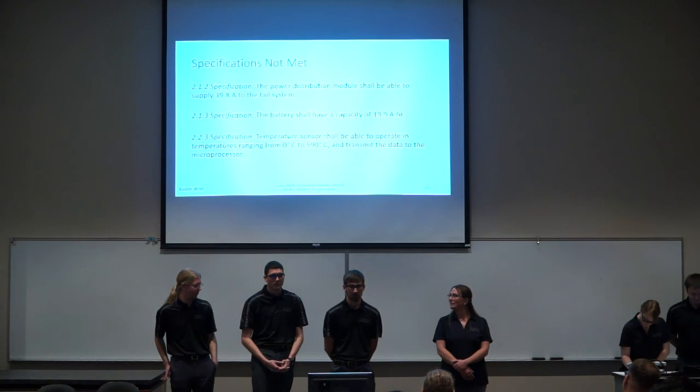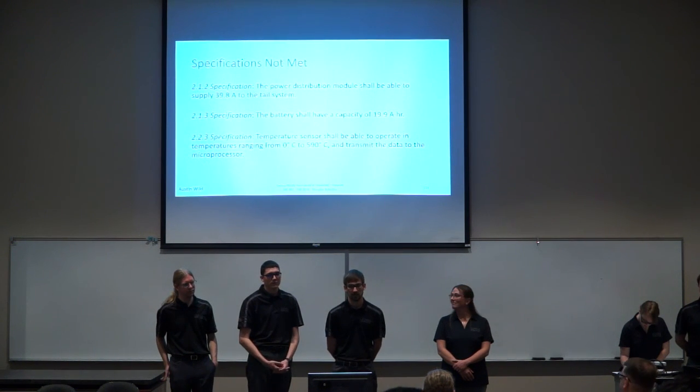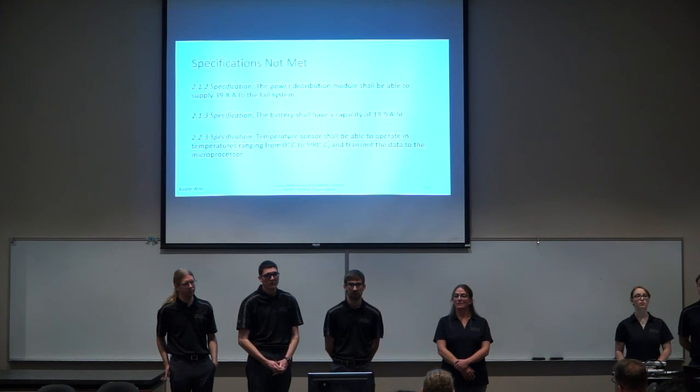In order to reduce costs in both money and size, we use a lower amp hour rating battery. What that affects is our battery life. We had calculated for a 30-minute battery life, but given both, we will be fine operating off 15 minutes or more with the batteries we have now.